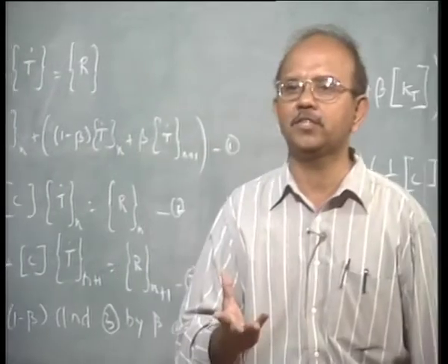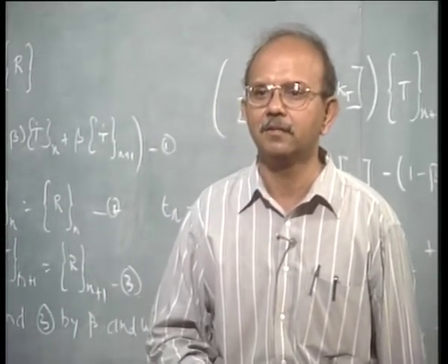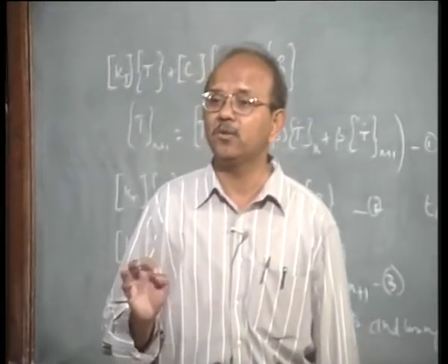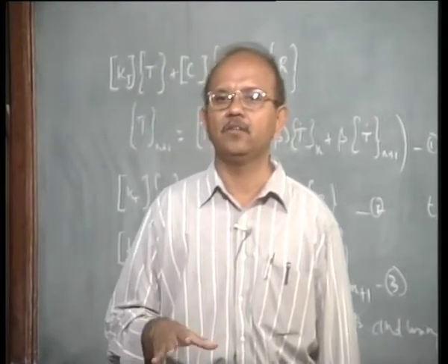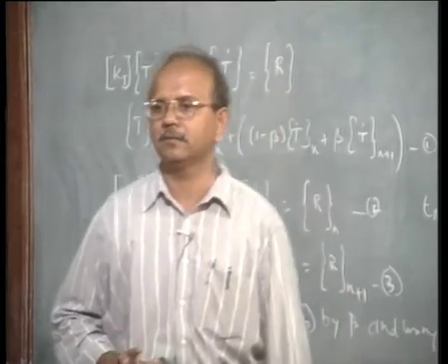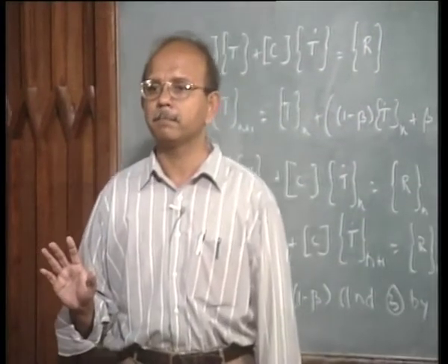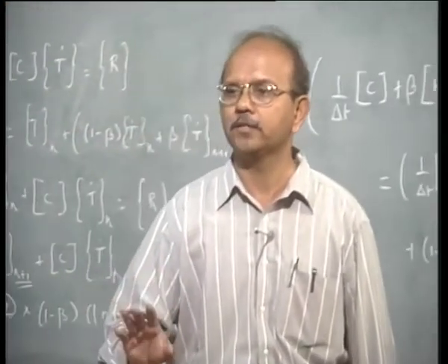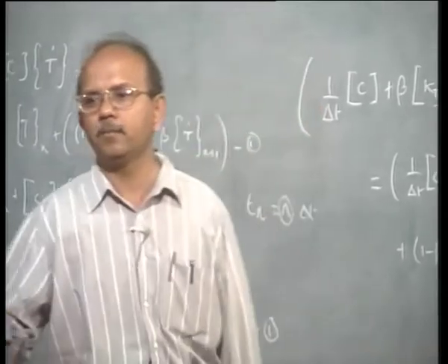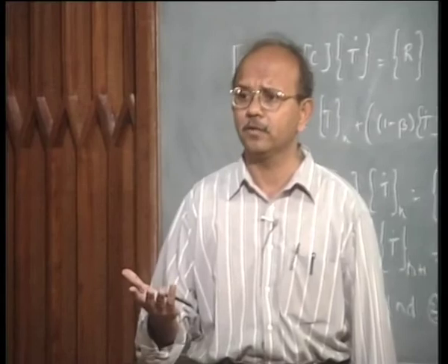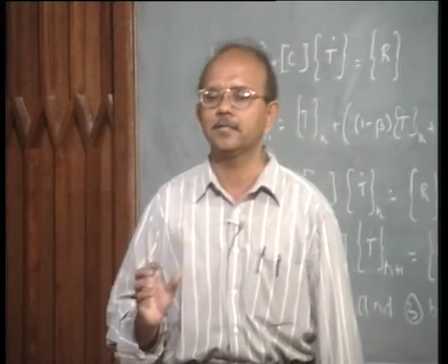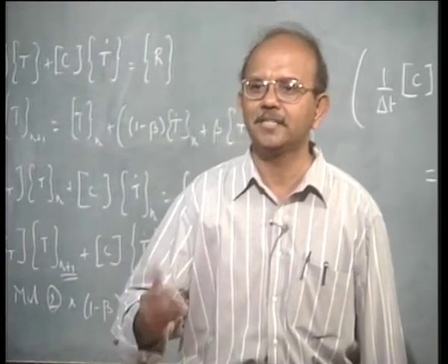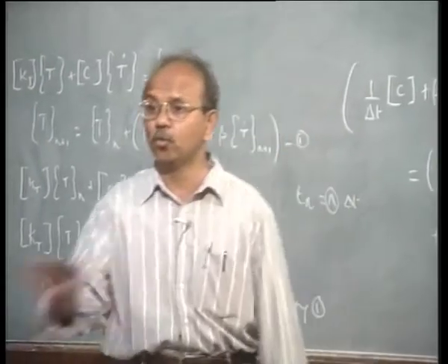On the other hand, if you want to do just a simple stress analysis, even involving things like contact, I don't think you need to check every time whether the result I have got is right or wrong. I think that is a waste of time. As long as you know finite element, of course I am not talking about mistakes you make, like choosing a plane strain element instead of a shell element, then it is a different story. As long as you know finite element analysis and apply it correctly, I do not think there is any need for you to go and justify whether what you have done is right or wrong. There is no need for it.